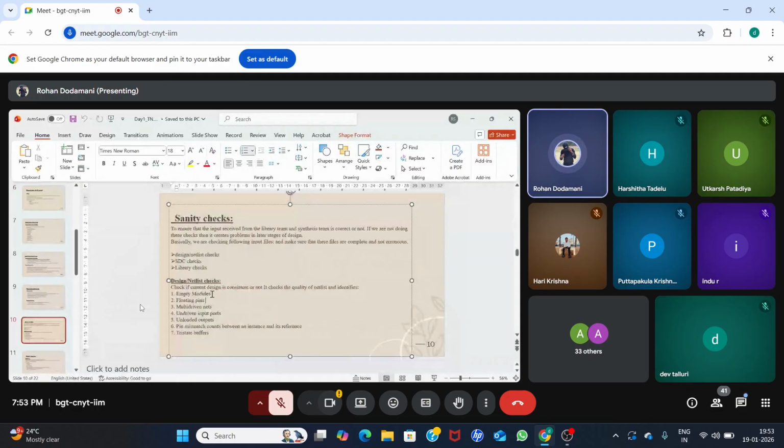So for that purpose, we need to check whether any empty modules are there or not. If we are not checking, the tool will do this by default. The tool will start checking whether empty modules are there in the netlist file. If any empty modules are there, it will automatically show in the console that empty modules are present. We do not modify any input files. If we get any errors like empty modules, porting pins, driven nets, or undriven nets, we need to report them to the synthesis team itself. They will take care of it, sort out that issue, and send it back to the PD team. So we can't modify anything here.